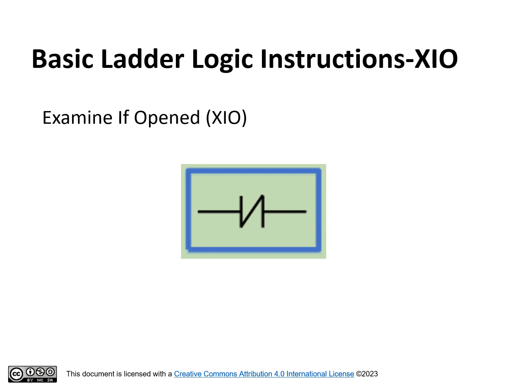This assumes that there are no intermediate instructions in between the input and output instructions. If the corresponding memory bit is a 1 or on, this instruction will not allow continuity and thereby de-energize the corresponding output coil. Again, this assumes that there are no intermediate instructions in between.